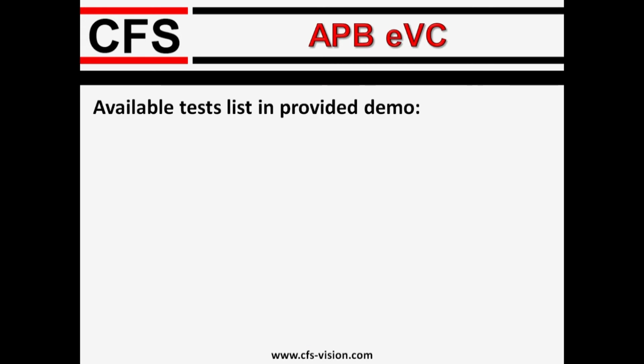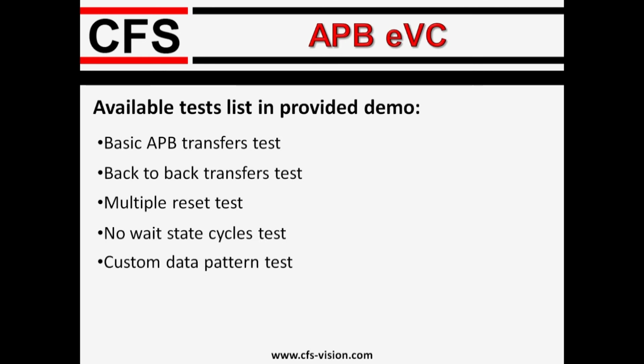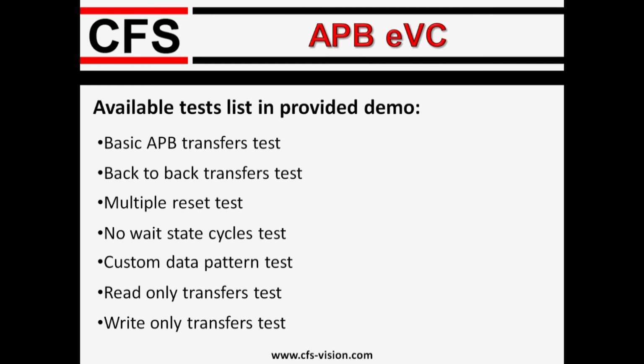These tests are basic read-write transfers, back-to-back read-write transfers, multiple reset during APB transfer, transfers with no extra cycles during the wait state, custom data pattern for read and write transfers, random read transfers, random write transfers.